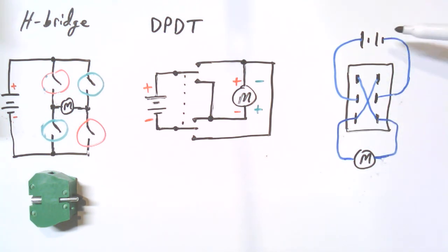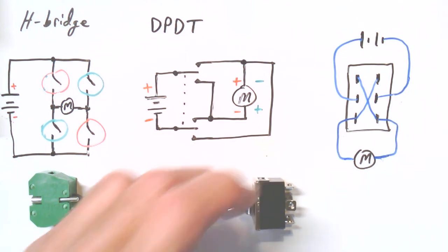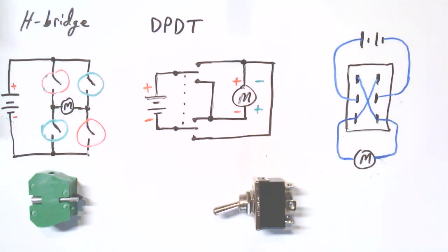Again, though, we could switch that. It wouldn't matter. I could put the source here and the motor here, and it would work the same. So these are essentially all the same thing, as is really the point of this video, or one of the points: all the different ways you might run into this same sort of switching configuration. I mean, if I had a relay, I could drop it on there too. But a mechanical switch, a relay, contacts, transistors, all are in the game.